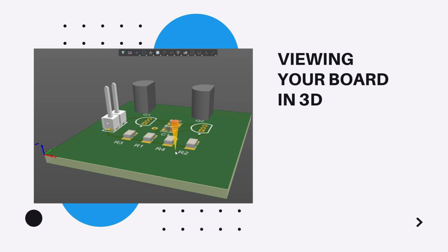Apart from component manufacturers' websites, 3D models are also available on community portal websites such as 3D ContentCentral and GrabCAD, where designers share models, and also a growing number of commercial 3D sites, including PCB 3D. If there are no suitable STEP models available, create your own component shape by placing multiple 3D body objects in the footprint.